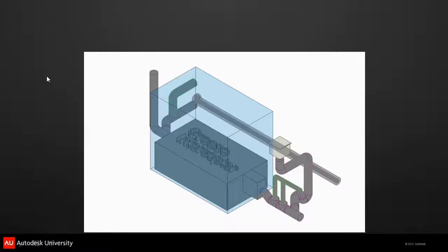Talking about families, obviously there's going to be a lot of opinions about this. We've talked about a good bit under the LOD. We had a family discussion up here. You basically want to think about where your connections are shown, and if it's a manufactured object that you're connecting plumbing up to, just make sure that you're not trying to model something at a high level of detail that's not the actual final product.